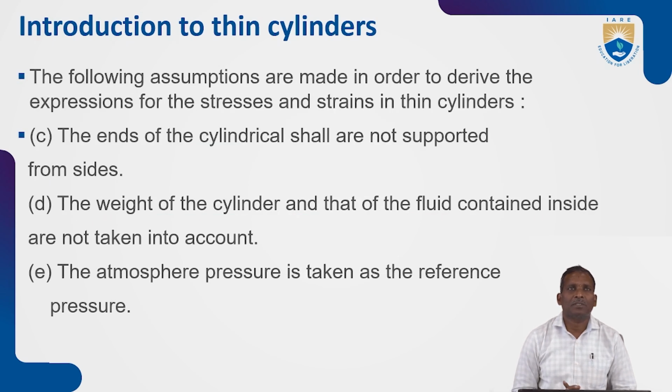Another assumption: the ends of the cylindrical shell are not supported from the sides. The weight of the cylinder and that of the fluid contained inside are not taken into account. The atmospheric pressure is taken as the reference pressure.